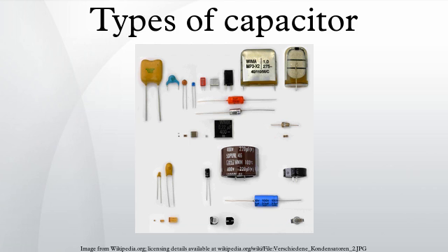Glass capacitors. The first Leyden jar capacitor was made of glass. As of 2012, glass capacitors were in use as SMD version for applications requiring ultra-reliable and ultra-stable service. Power capacitors. Vacuum capacitors are used in high-power RF transmitters. SF6 gas-filled capacitors are used as capacitance standard in measuring bridge circuits.